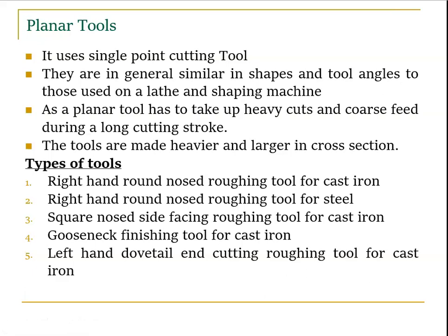Right, the planer tools, as similar to shaping, planer tools are also single point cutting tools. So இதுவும் single point cutting tool தான். They are in general similar in shapes and tool angles to those used in the lathe and shaping machine. As a planer takes up heavy cuts and more speed during the long cutting stroke, tools are made heavier and larger in cross section.